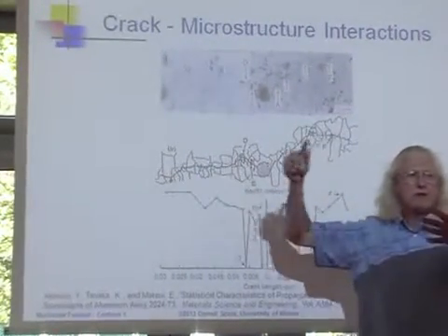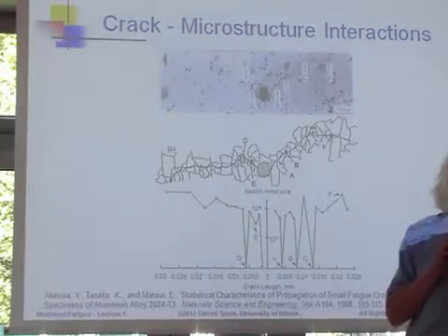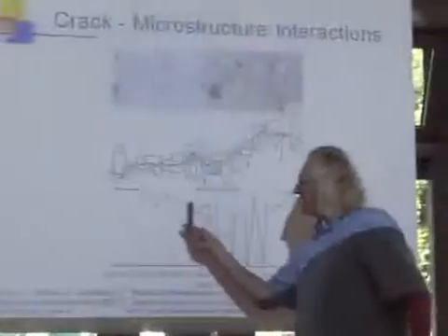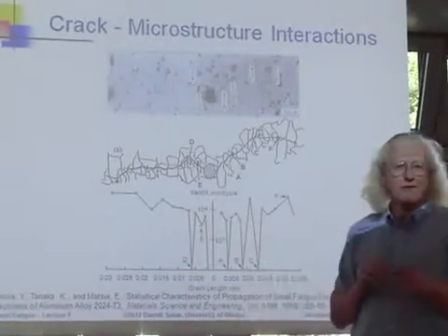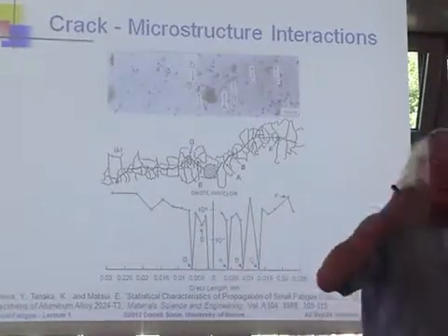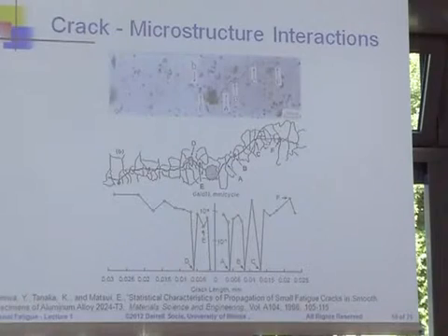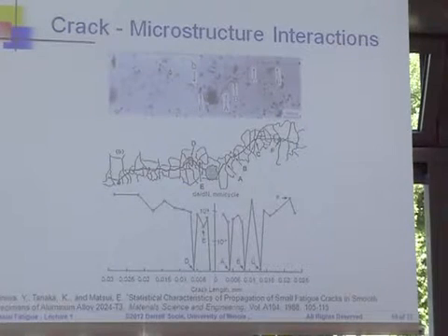Right? And that's the region dominated by this crack plasticity. The crack is big enough that it can grow on its own. But that's not always where all the lifetime is. All the lifetime is when it's small. So it's easy to analyze out here. Easy to build models for what happens out here, because now we are independent of the microstructure. When we're out here, the microstructure really does look homogeneous and isotropic and all those things we assume. But not when the cracks are small. So when you are less than maybe 10 grain sizes of the material, then you'll have a lot of variability in the growth rate as these microcracks interact with the microstructure.